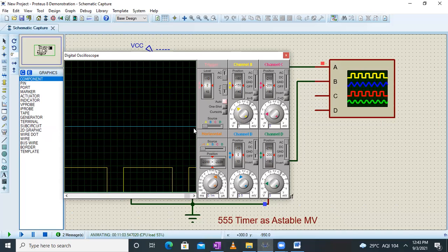It's very difficult to determine. So here is a reference level near this horizontal line. So let me keep a reference level as this green, just for reference, okay? Not for any calculation. Let me keep it over here as a reference level, and then I'll count the divisions. Now I'll put this ground to DC. So when I go to DC, this is the level I want to check, right? So I'll count the divisions now. It will be around 1, 2, 3, let's say 3.4 it is.